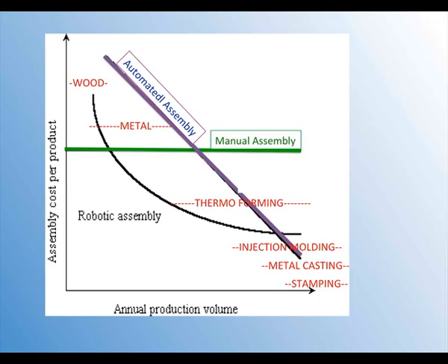We all assume that as the volume for a part goes up, the cost per part should come down. But what's the real mechanism behind this? So if we're talking about a manual assembly operation, we're talking about a job shop where every part is one-off. The operator works on one part at a time. Your costs for a manual operation are pretty much fixed. There may be a slight learning curve with the initial couple of pieces, but really you shouldn't expect to have a significant decrease with volume.